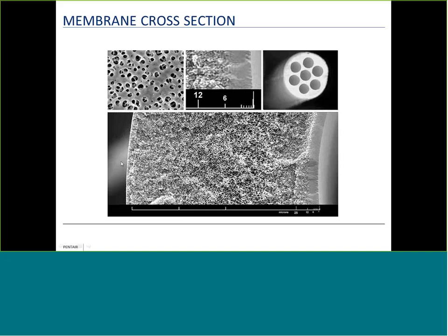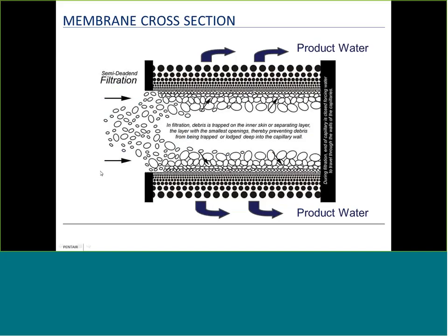The Endurance SC comes with a UF pre-filter with a programmable control that has gallon settings, allowing you to set the gallon flush cycle based on the incoming dirt load of the water. Comes with its own accumulator tank for storing filtered water, still chlorinated, because it hasn't gone through the carbon filters yet, to use as backflush or as a partial surge tank for flow out to applications.